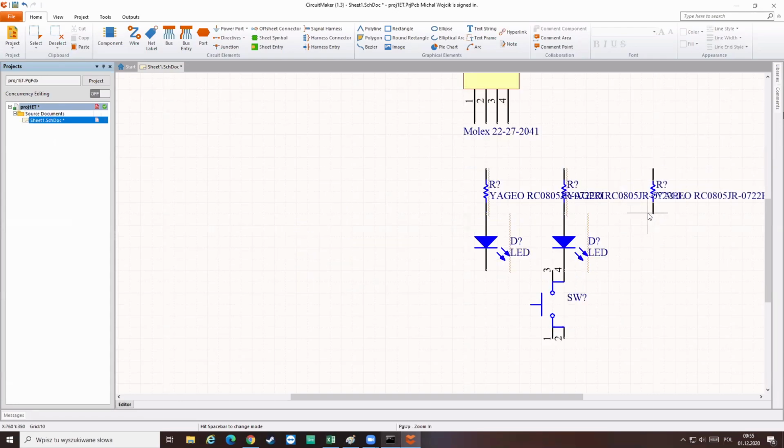Okay, now how to wire stuff. Here is the wire, so you just select the starting point and click it. Now, I'm not holding the left button of the mouse. I just clicked once. We'll do it again. Wire, just clicked once, move it around, and search for the next tip to go. Okay, this one. And I'm connecting this one and this one to this one.